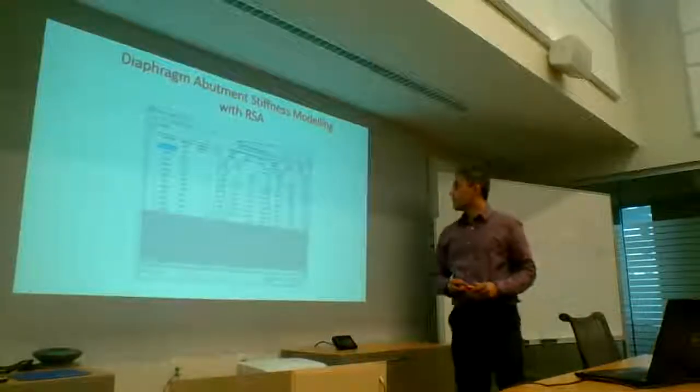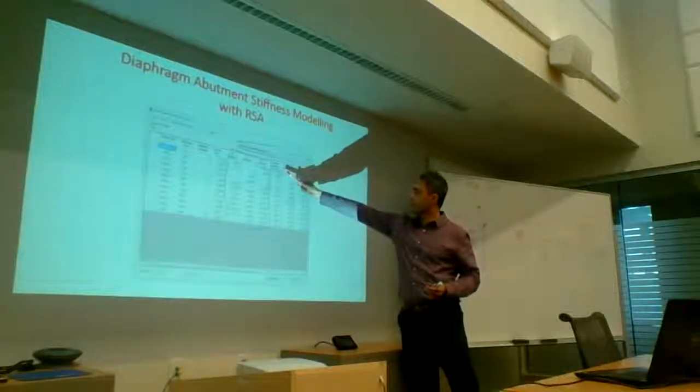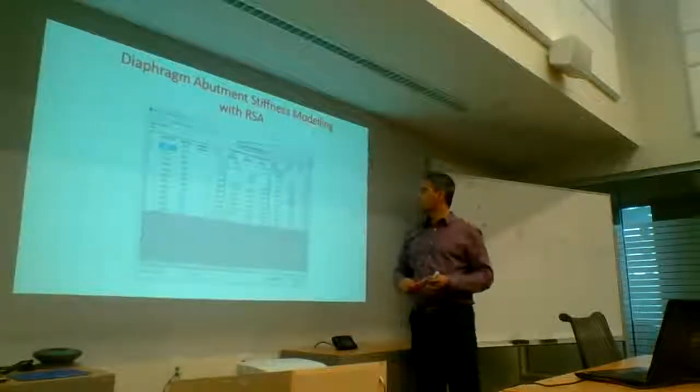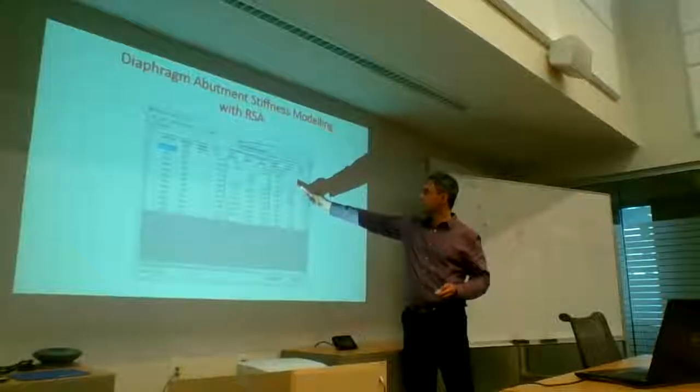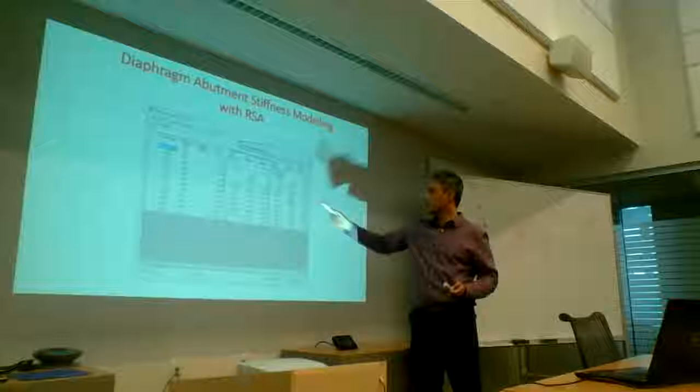Okay, so 90% mass for this one here, you can see in the very first mode, you get 99%. And in the very first transverse mode, you get 82%. And then the seventh mode gets you to 93%.